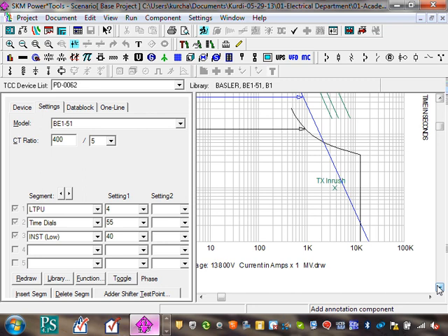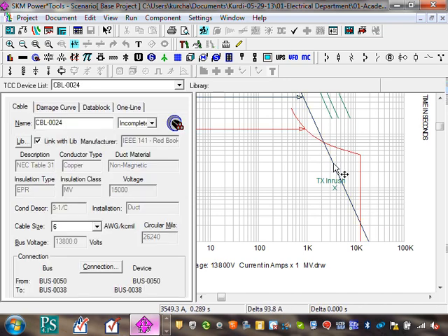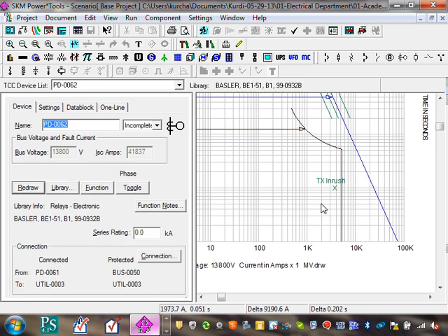So in a case like this, in order to adjust, you have to go to your curve and increase the size of your cable. My cable is number 6. Look, I'm going to go to number 1/0. Number 1/0 almost can't make it here. Or I can adjust my instantaneous. Can you guys see how I can adjust my instantaneous? I can put my instantaneous right here. Now I have full protection for my curve. Big deal when it comes to protecting your curves.